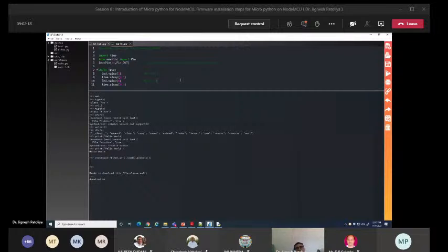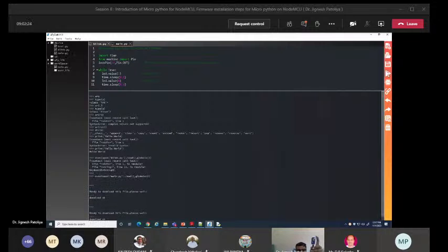Now again stop. Now again I click on download and run. Sir, please acknowledge me. Is this lower LED blinking right now? Yes or no? Yes, sir. It is blinking. Okay. So these are the onboard LEDs. In the case of this NodeMCU, we have two LEDs on board. One is the on-chip module LED, and the second one is provided by the PCB of the NodeMCU. Now again I stop it.